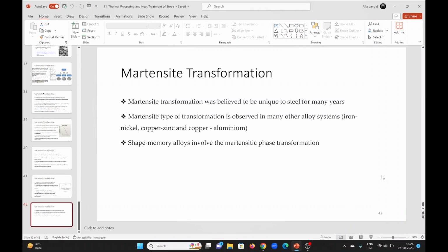Not necessarily. In plain carbon steels only, you get the ferrite phase. Other steels are also possible. For example, if you add a high amount of nickel and manganese, they can make different phases such as austenite. They are austenite stabilizers, manganese and nickel. They reduce the A3 line to very low temperatures, and they make austenite stable even at room temperature.